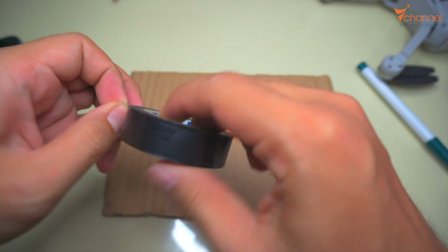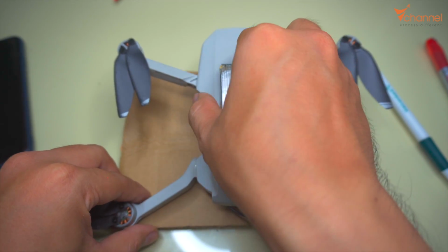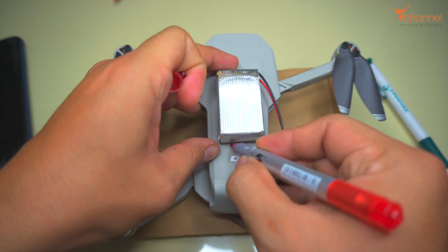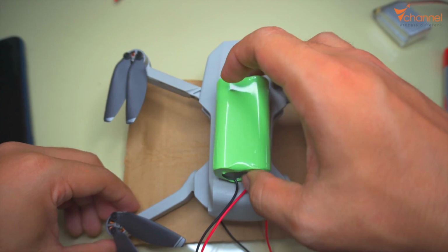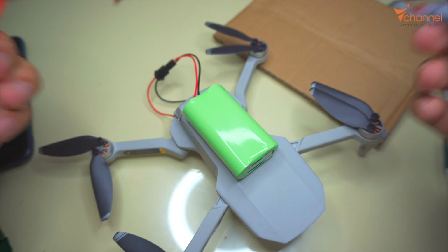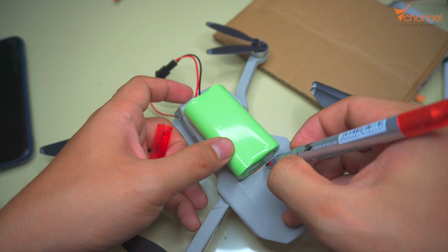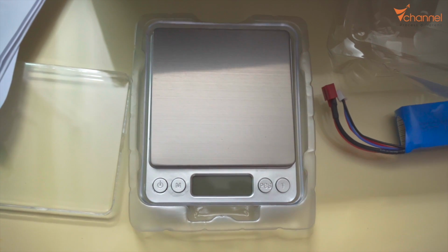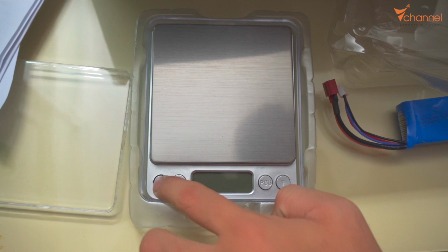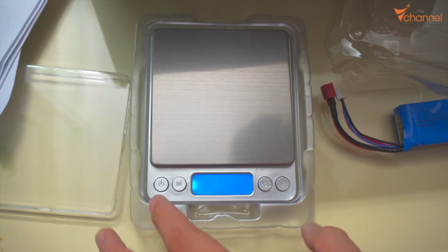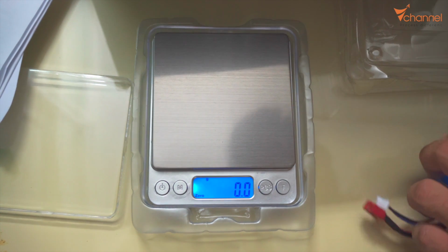And we should find the best location to put the battery, because if it is not placed right at the center of gravity, one or two motors will suffer higher pressure. We must take the risk of overload, unstable flying, and in strong wind it can even go out of control. And the very important thing that I taught in the previous part is the weight suitable for the new battery. So now we put this battery on to see how much is suitable for the Mavic Mini in sub level.